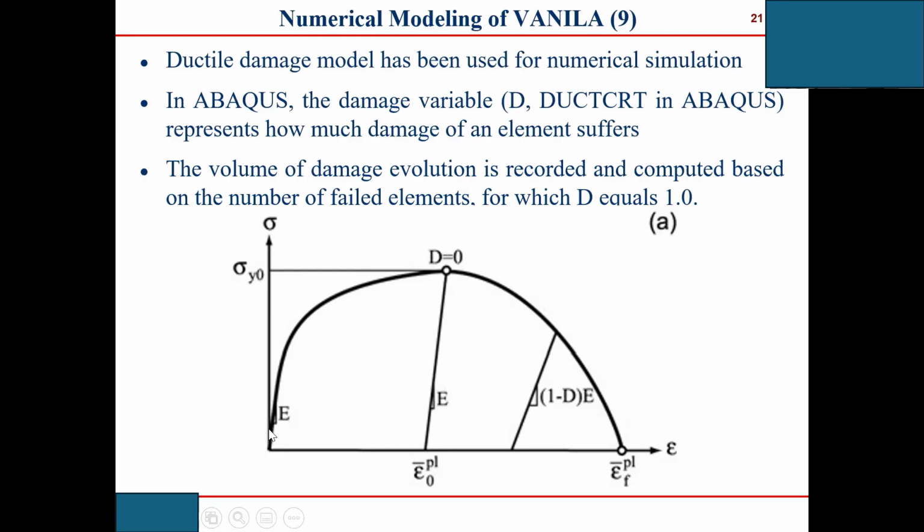Look at here. We are familiar with this curve, right? This curve is the strain hardening. So this is the yield stress. This yield stress here is used, so this is Y0 here. And from here, if you just take away your load, the material is going to behave this way. So this line is parallel to this line. That's the reason the slope we use is Young's modulus.